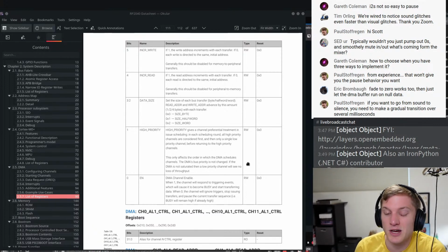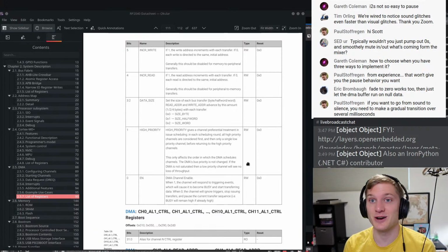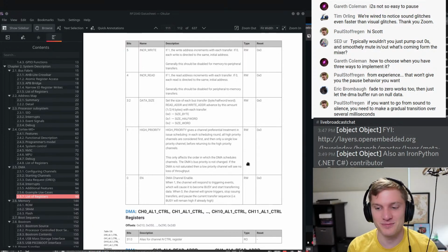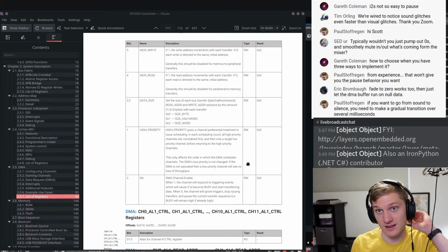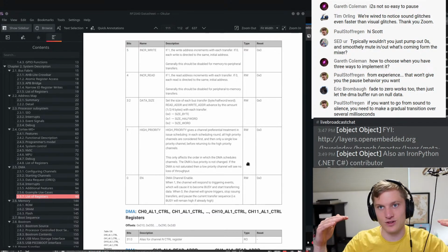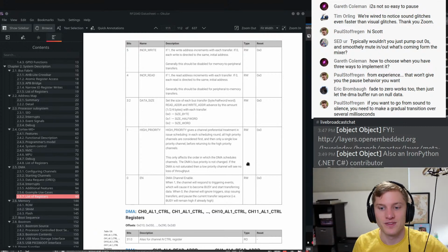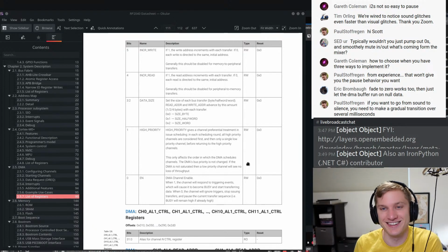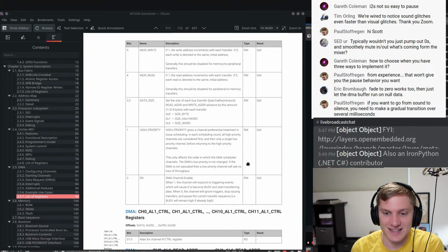We're not spectacular about it. If you're an audio person and you care about this stuff and you want to work in C code, we have places you could help us for sure. There's a to-do in the NRF that says when you start up, ramp to the quiescent value. We allow you to specify a quiescent value, which is the value you want us to start and stop at. But there's a to-do in there that says ramp to this value. We don't right now. So yeah, if you're really into audio stuff, Paul's Teensy library is really good.